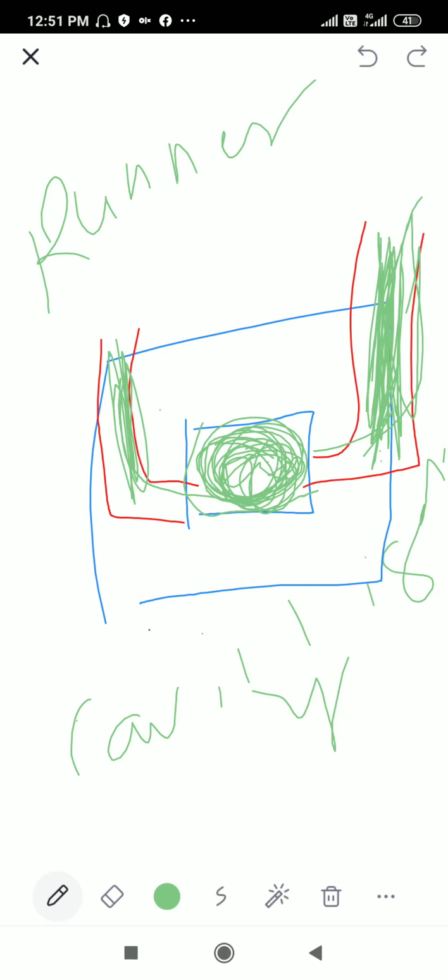Okay, the size starts to reduce as its solidification starts. At that moment, some of the liquid material is supplied back to the mold cavity, since maximum shrinkage will occur, and the molten metal can compress or shrink. To avoid the shrinkage defects, or to overcome the shrinkage tolerance, this riser works like a reservoir.